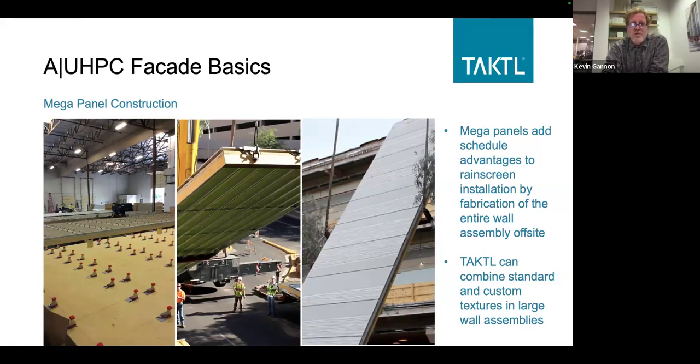There were circumstances with the site that I won't get into that drove a prefabrication with units of this size. But on the left, you can see the water barrier with girt brackets installed. And then as you go back into the perspective of that image, you'll see insulation on that, and then rails, and then panels.